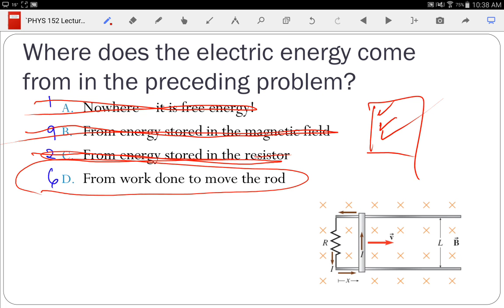So why did it happen? It turned out that while there were, I think, 13 grounding rods, around half of them had been left in place. People just checked off saying they were gone when they were still there. And so when they turned on the power, they had a direct short between their high energy output and ground. And that meant that you had a huge amount of energy dissipated through those big metal rods.